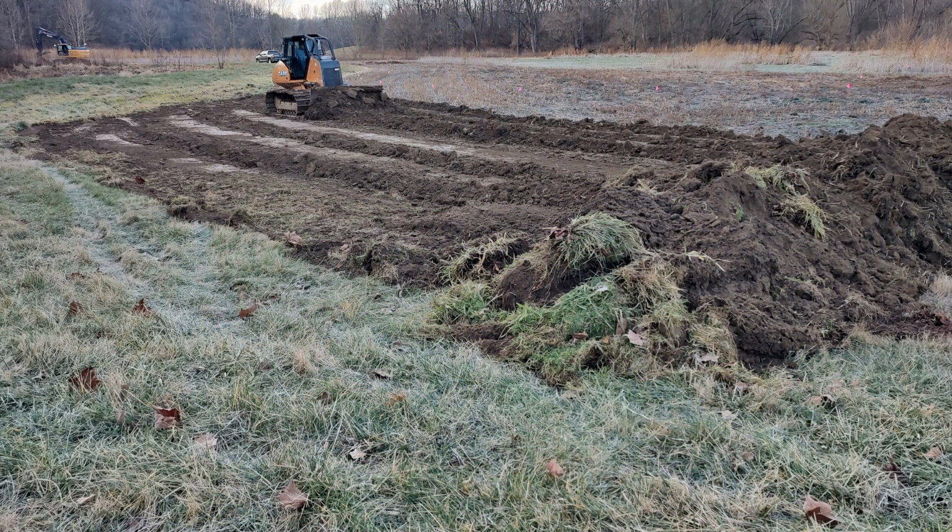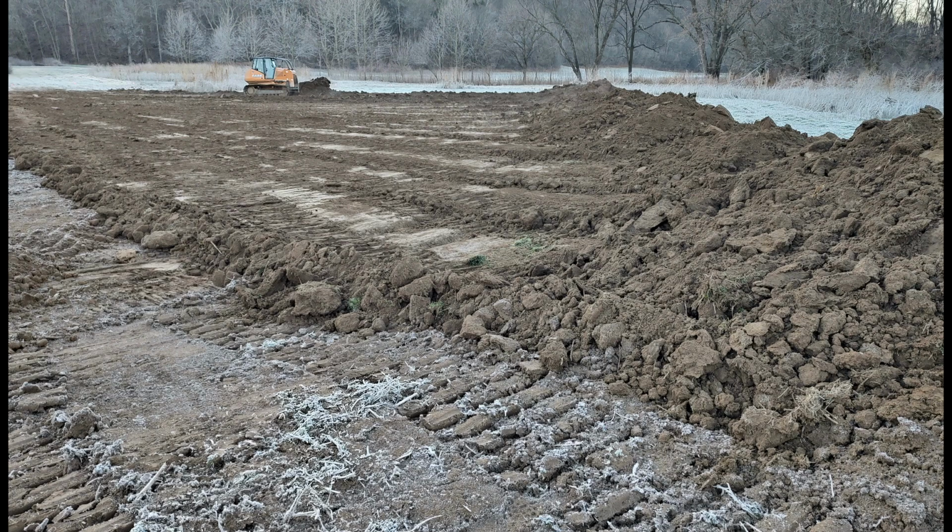Here a dozer is being used to remove the topsoil from an area where the groundwater dam will be built. The topsoil is pushed into a long pile we call a windrow for later placement in the finished wetland. The dozer removes topsoil from an area about 200 feet wide that includes and parallels the location where the core trench is going to be dug for the groundwater dam.